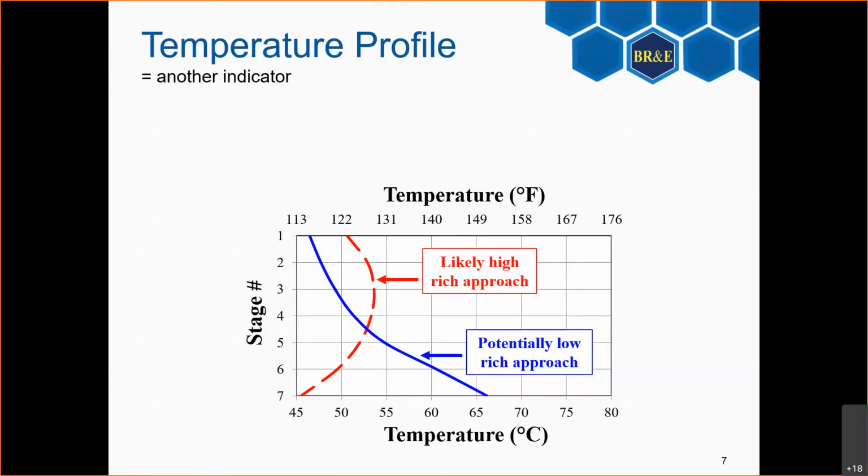And if they're happening in this location, it tells you a couple of things. First of all, you are dangerously close to the top of the absorber, so you're close to acid gas breakthrough. And also here, not too much is happening, which probably means that by the bottom of the absorber, you're running out of amine.